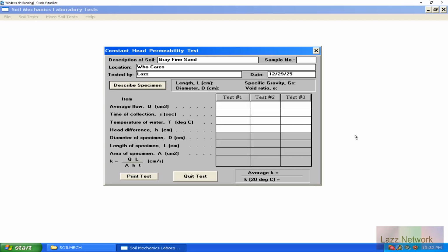And it has a set distance between those ports on the exterior, which flow water to a manometer that just has a series of numbers on it. Usually it goes to the 10th. And then, as you take your readings, you're also going to record your manometer readings for your first one and second one. That'll tell you what your head is, or what the value of H is, which is your head difference.